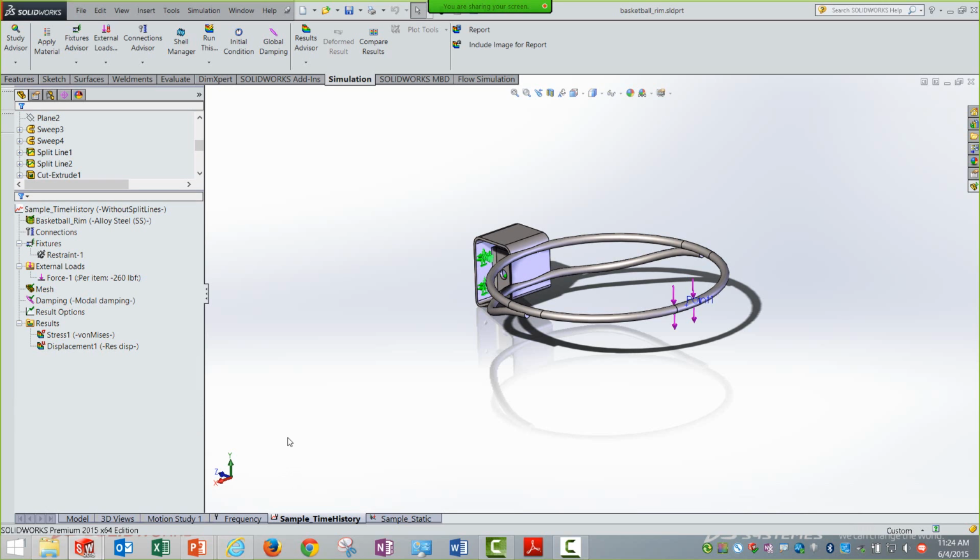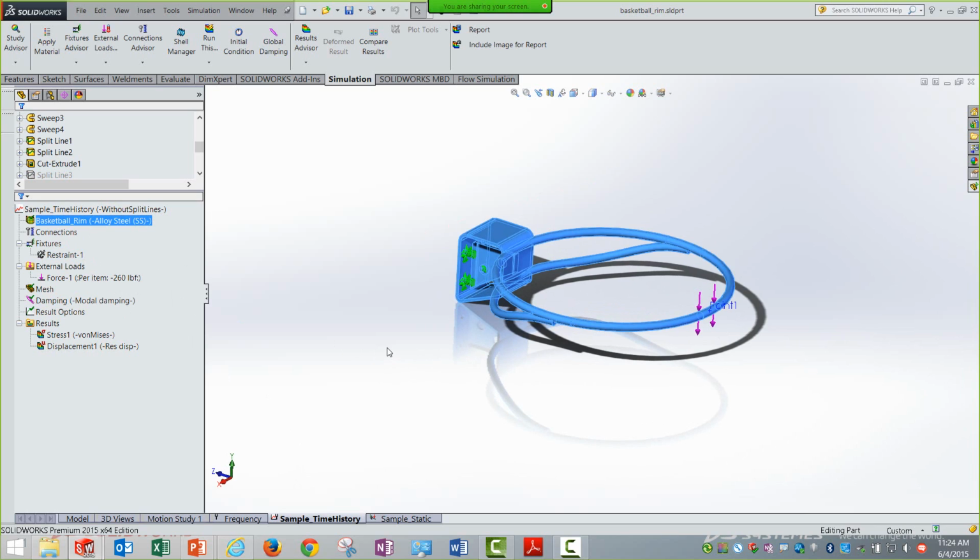Today we are sticking to linear dynamic analysis and applying this force using time. So restraint, as we discussed, is as it is. Material property is nothing different because this is a linear dynamic analysis. By the way, in nonlinear dynamics, we can actually simulate nonlinear material as well.